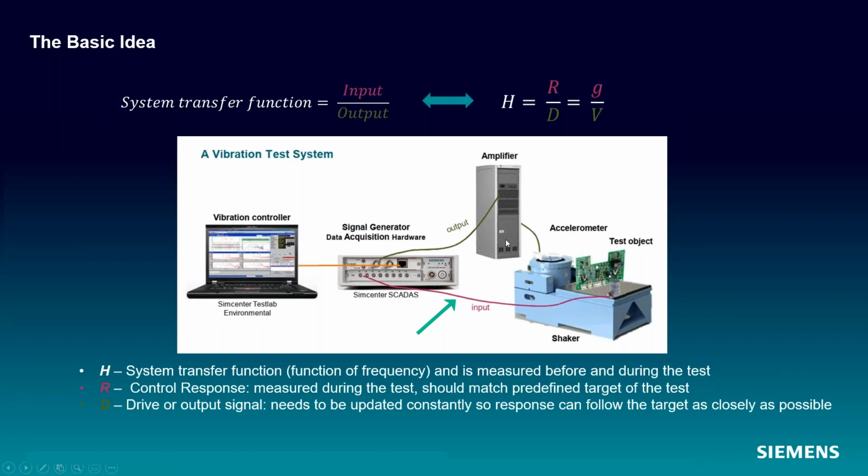So we run what's called a pretest or system identification, and then that signal gets used as a basis for the first drive signal. Very basically, we send out some voltage signal to the shaker, we measure the response, and this happens open loop. We're just putting a signal out and letting the shaker do whatever we want.